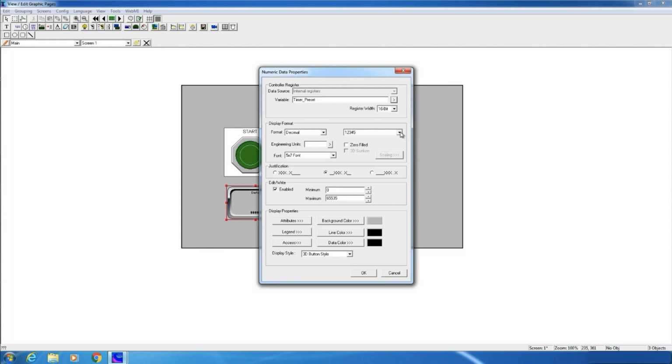Let's just go ahead and leave it long here. Under engineering units, well, actually though, if we're going to display it in seconds, we should put a decimal point in there. So let's just go ahead and pick this guy, 4 digits maximum to the left and 1 digit to the right. Our engineering units, we'll go ahead and make this in terms of seconds. We'll make the font a little bit bigger. Okay, we'll go ahead and center the value.